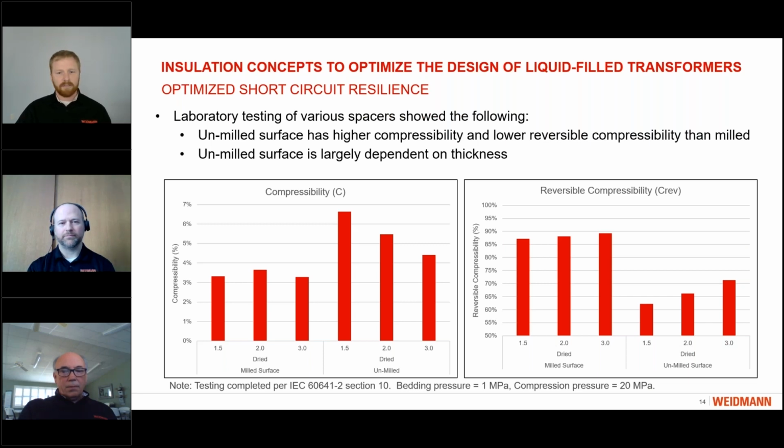When we look at these materials in the lab, we did some laboratory testing of various spacers and looked at a number of different things related to compressibility. For reference, this testing was all completed per the IEC standard. We're using a bedding pressure, an initial pressure of the spacer stack, of 1 MPa, and then compressing that stack up to a pressure of 20 MPa, and measuring the difference between those two.